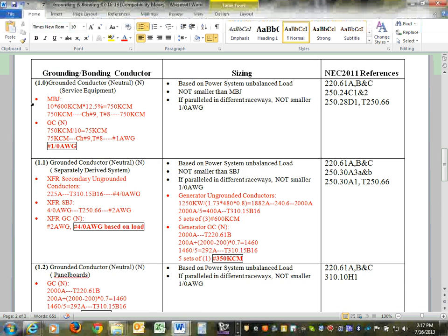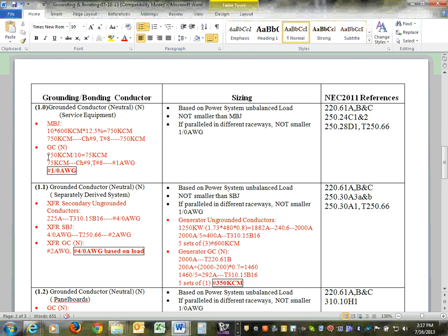We're here at the service. So now you have 4 conductors carrying current in a conduit, and if your neutral is carrying an unbalanced current between the 3 phases, the code says you don't have to calculate it. Only if it's carrying harmonics, and at the 4000 amp level, you can easily consider it a non-current-carrying conductor. And even if you do derate, you're going to see that your conductors will be okay. This is the least of your problems.